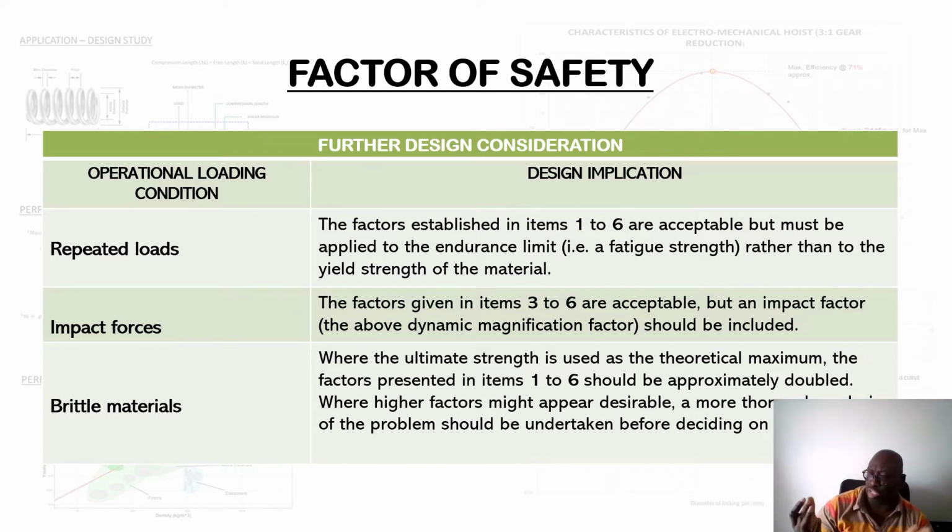I did make mention of fatigue. Not all materials have a defined fatigue limit. So this is where you probably need to think about what the ideal safety factor would be for a given component if you design with respect to fatigue. These are some of the design issues we need to think about when it comes to designing and engineering components.